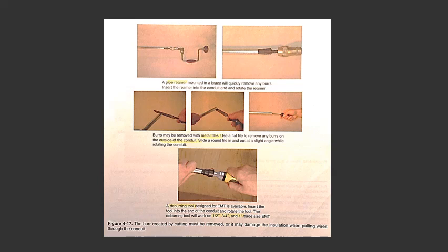Bending metallic conduit. The purpose of bending conduit is to route it around corners and over obstructions. There are numerous special manufactured fittings available that could be used to achieve similar routing, but field bends are preferred. A field bend is a bend that is made on the construction site. This generally saves time and is far more economical than installing fittings. Most bends in EMT are made with a conduit bender.